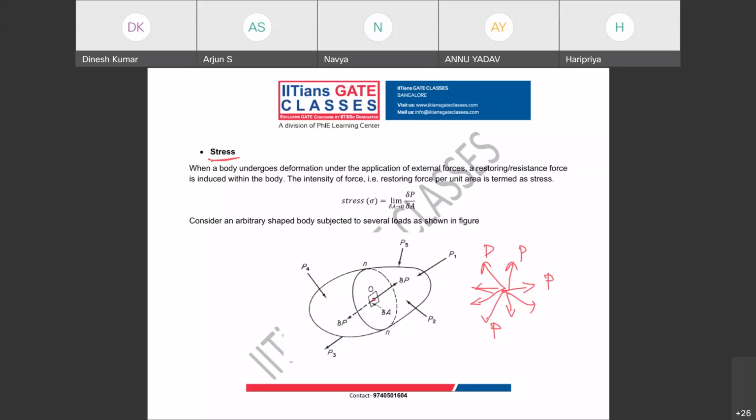Now, if you say in simple words, if it is direction dependent, is it a vector? Yes, sir. No, it is not even a vector. It is something called a tensorial quantity. So that is what we are going to see. What does it mean by tensorial quantity, guys? At a point, your stress will require three things.